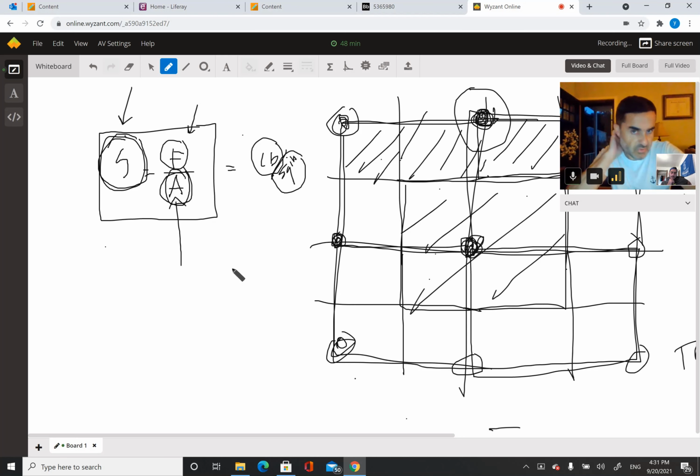Now, I can make assumptions. I've done this enough that I know a 10 by 10 column for a 30 by 30 span would probably work, like a W flange, a normal weight, like W10 by 28, because I've done similar sizing on past projects.